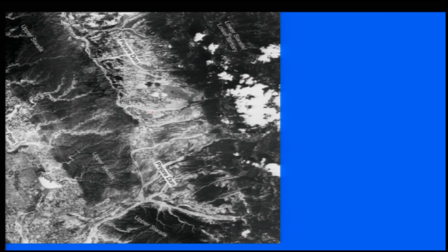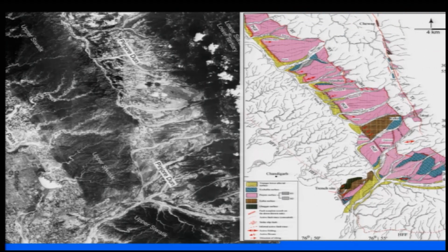and then we also see multiple terraces. So viewing this in 3 dimension using the high resolution satellite photo with stereo vision, we prepared this map, where we have extracted drainage and the landforms here. And the more striking one, what we will see here, is this portion which has been marked here, the right bank of Gaggar river. It shows presence of multiple terraces.